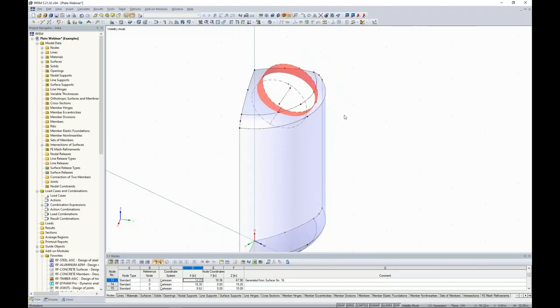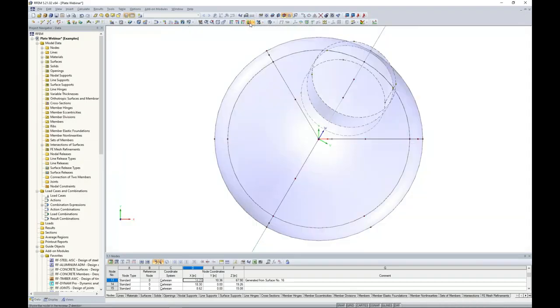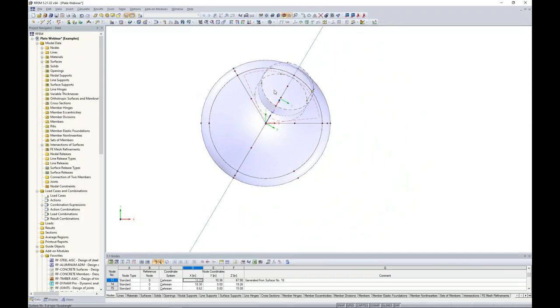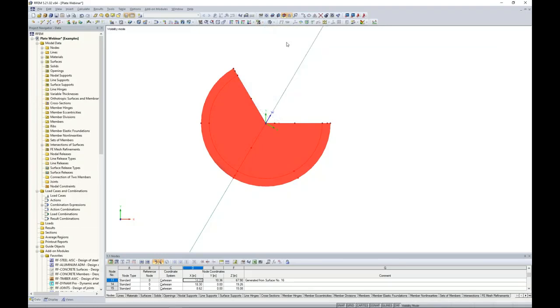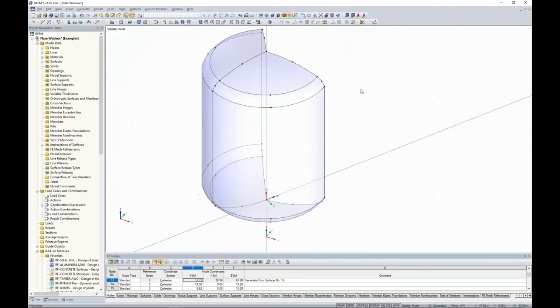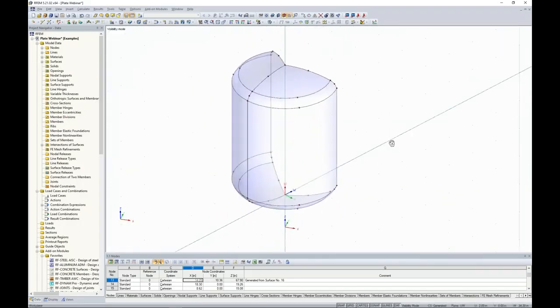Okay, so now we have completed the modeling of the manhole. So I'd like to go back to our full view here by canceling my visibility mode. Let's turn this back into a plan view, looking down on the top of our structure. And now I'm going to select the additional 2 quadrants here to begin modeling our lifting lugs. And I can choose the visibility by selected object. So now you'll notice that my manhole in that quadrant is completely hidden.